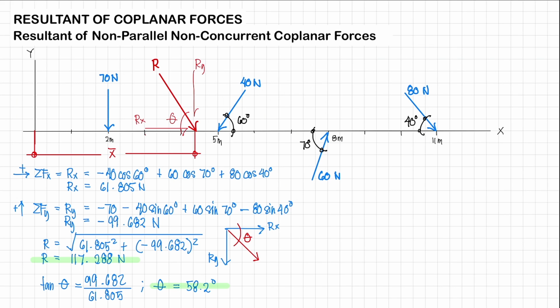All right. So to solve for bar x, again, we're going to be applying your Varignon's theorem. That means that, let's use a reference axis, this reference point at point O. The moment at O due to R is going to be equal to the moment due to all the forces.